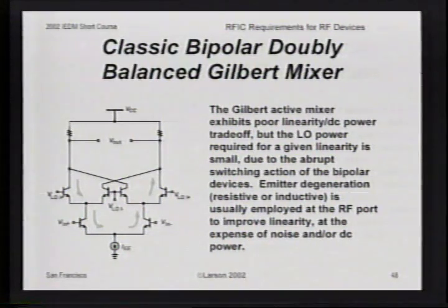As Professor Abadi mentioned earlier, it's absolutely crucial to keep the size of these devices very small to get the best possible linearity and noise figure out of the circuit. And so this topology is very commonly used, and from a circuit perspective, the route to improve performance is the same route that I mentioned for the low noise amplifier before. Using harmonic termination techniques, we can improve the performance of the bottom portion of this mixer without increasing the DC power or hurting the noise figure. And that's an area of some active research by a variety of groups.